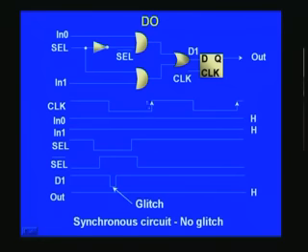You should keep in mind the total delay of this one, and then only select your frequency. Frequency of operation is governed mainly by the total delay that you encounter in a combinational circuit, and if you take this into account, then you can always condition your whole circuit in such a fashion that whatever glitch appears will be ignored, and only the steady state value is registered.